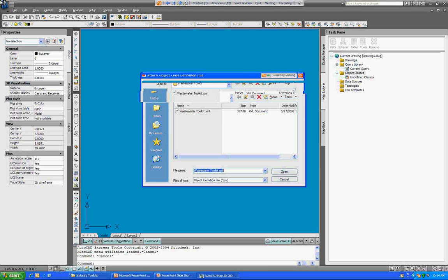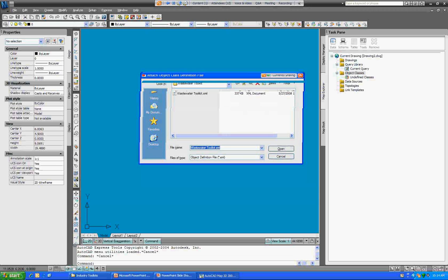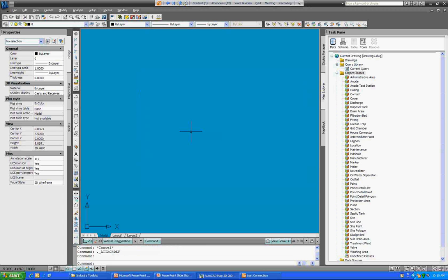So we've got a new blank drawing here. And let's pretend that we've got some existing drawings out there that we'd like to classify using this data model. Now there are several ways you can do it, but keep in mind those drawings probably weren't started with this drawing template, so they're not going to have the blocks and the layer standards. So one way we can work with those drawings in the Map 3D environment is to attach those drawings through our attach source drawings functionality in Map 3D. So let me do that.